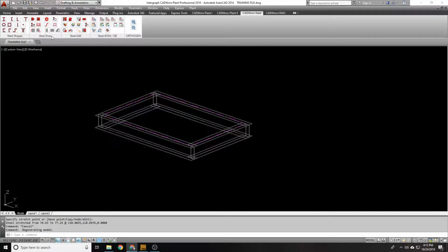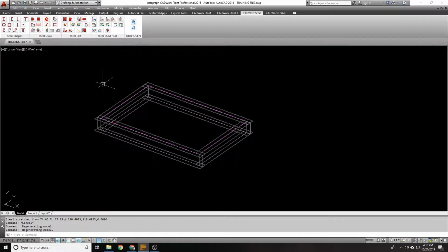Creating handrails with the handrail tool can be really handy and helpful and make quick work of things. However, there's one caveat. Creating handrails with angles is not exactly advised or recommended because CADWorx doesn't handle angles all that well, like it does with pipes. But if you're doing pipe handrails, I highly recommend the handrail tool.